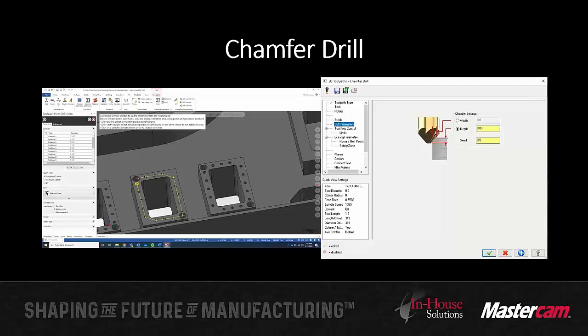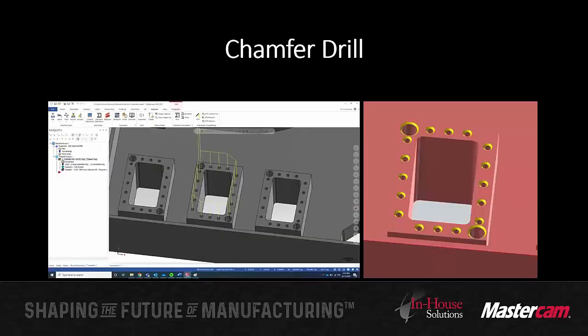As you can see in the image on the left-hand side, we have selected a couple of different size holes. In doing so, within one toolpath, it'll automatically chamfer all the holes for you. This is super handy when you're just doing a simple edge break operation, where you just want to break your edges, 10, 15 thou type thing, irrelevant of the hole size.